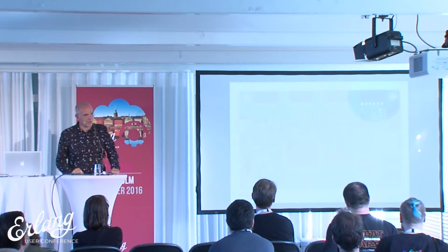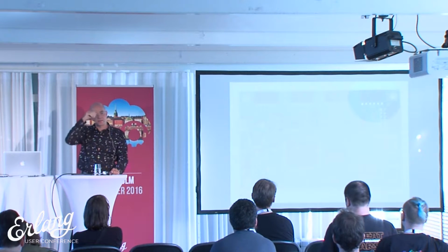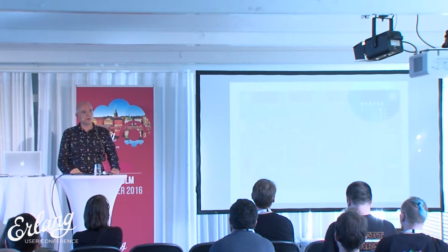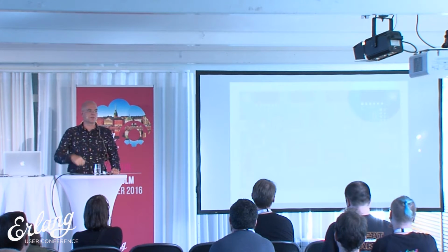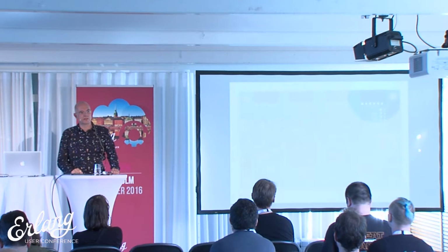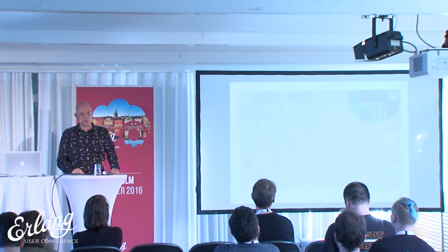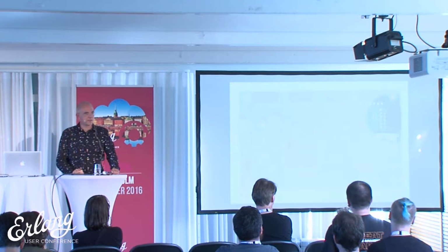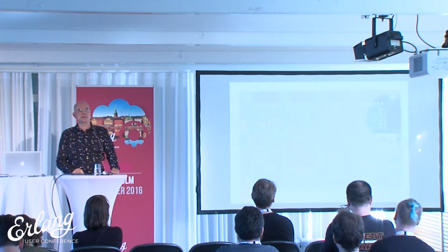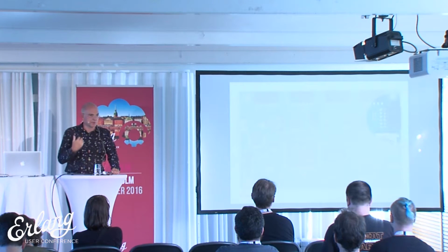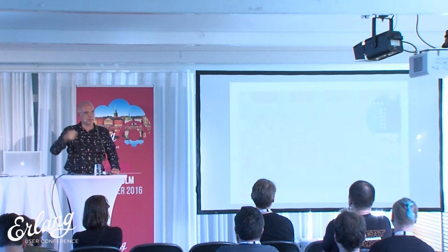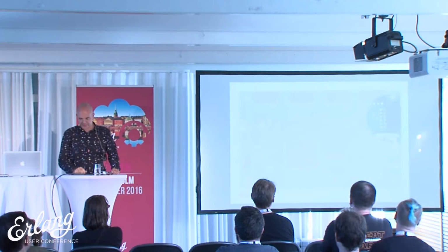The next one is SPI. SPI is an interface which is almost as simple as GPIO, but gives you more options because it's serial, and you basically shift bits out with the clock, and lots of chips directly support SPI. So since there are a lot of chips that support SPI, there's a second SPI. This one is a little bit higher. It's an extended SPI. It has two interrupt lines as input. So basically, your chip can interrupt back and say, I have some data for you, and then you fetch it with a synchronous serial thing.